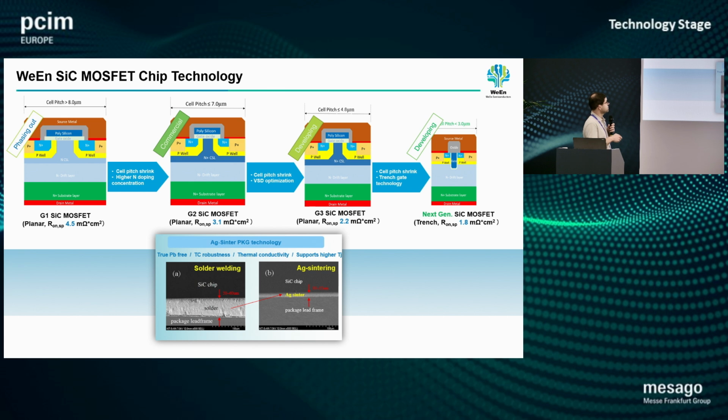Each of these layers adds thermal resistivity, so the device is not really able to dissipate thermal energy. And on the other side, you also have the fact that it also has a higher resistivity, so you have more losses. So they don't really help each other. So what we're really doing is reducing these to be able to have a better thermal dissipation.